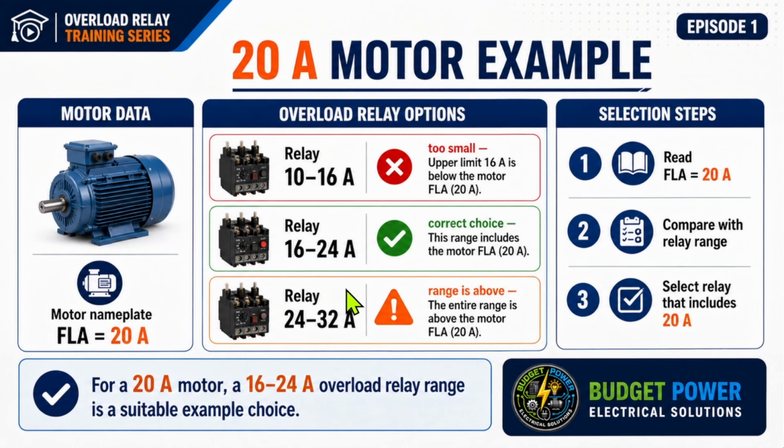First of all, I want to emphasize that we have to begin by finding the FLA, and after finding the FLA, we select the overload relay. That's my goal for you.